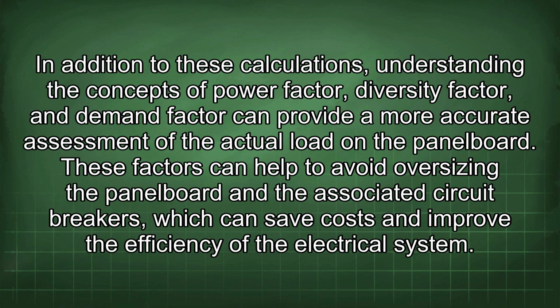In addition to these calculations, understanding the concepts of power factor, diversity factor, and demand factor can provide a more accurate assessment of the actual load on the panel board. These factors can help to avoid oversizing the panel board and the associated circuit breakers, which can save costs and improve the efficiency of the electrical system.